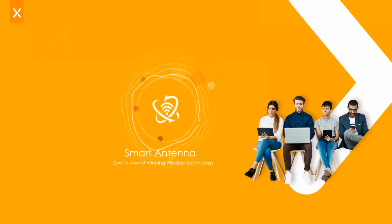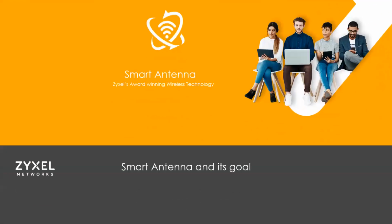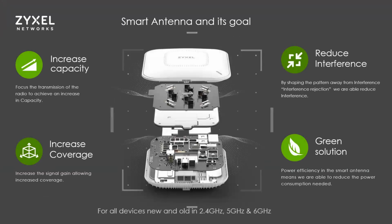The other technology we have here is smart antenna. For those of you that are familiar with Ruckus's BeamFlex and BeamFlex Plus, our smart antenna is a similar technology to that. The idea behind smart antenna is to create the best performing wireless antenna solution that you can possibly have. It's designed to help increase capacity, both the number of client devices that can connect to the AP before you start having complaints, as well as the number of APs that can fit into a small area, increase coverage, and with our algorithm that we use, the ability to reduce interference.